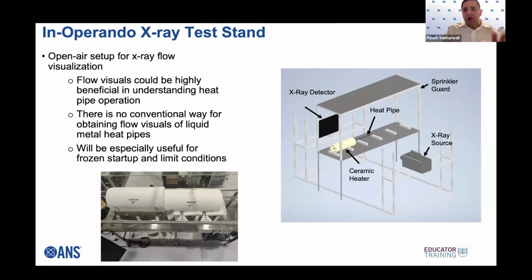After doing that test, now we are also looking at some X-ray tests, this in operando. So how would this heat pipe behave when you can look, when it's running? So basically when it's in operation, right? There's a wick structure in it. I'm not going to complicate things. Think about, you want to understand the flow inside, right? If I thermal cycle things, there's one thing to run something steady, but if you thermal cycle things, things might not behave as you expect them to behave. So you want to understand what led to the failure.